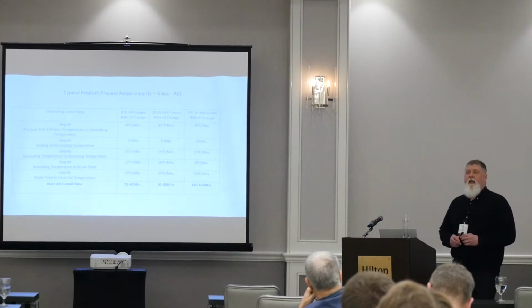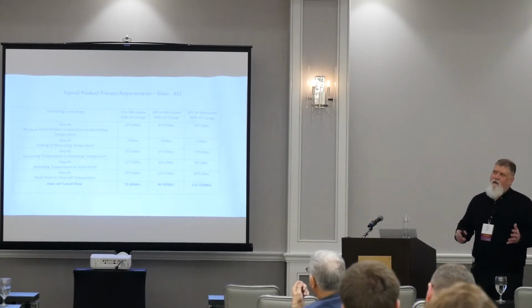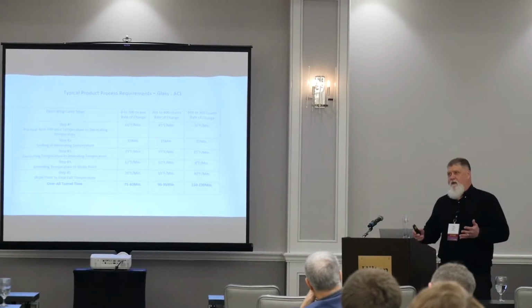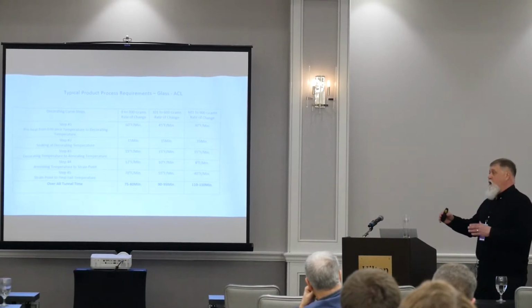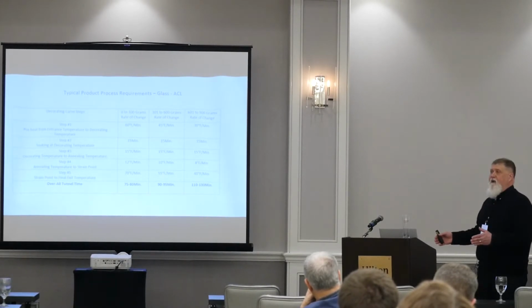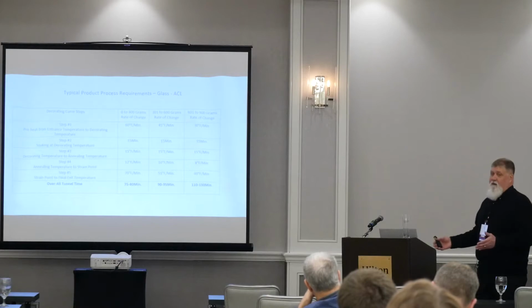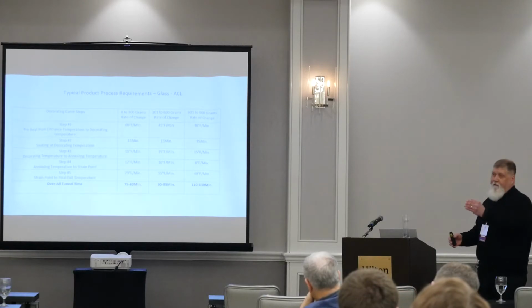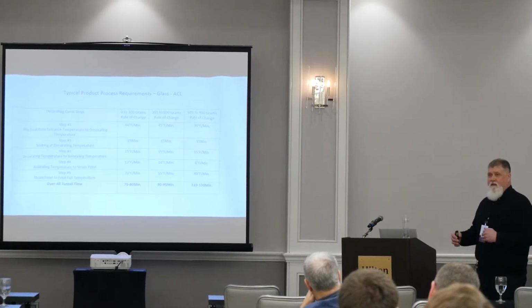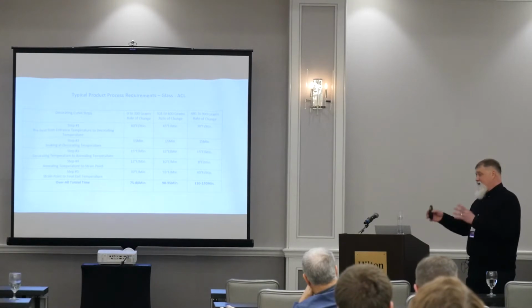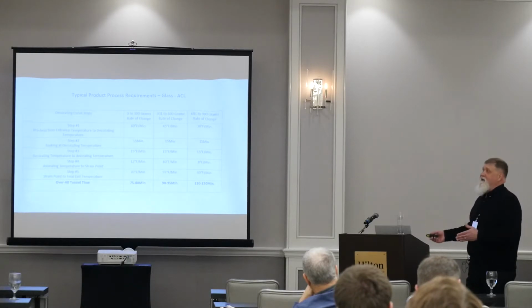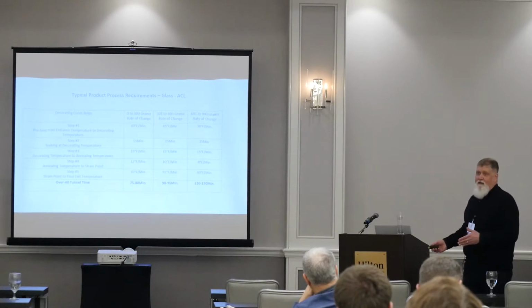And I guess that's another point to make for everybody, that I do still sometimes have conversations with different decorators: if you are working with soda lime glass, and firing it at those high temperatures, you are determining the final grade of annealing, or the amount of thermal stress that's in the glass. Whatever it showed up with from your producer, you are changing that. So if it's well annealed glass when it comes in, it can leave your plant well annealed, or it can leave your plant poorly annealed.